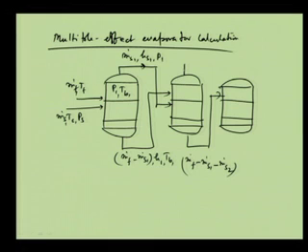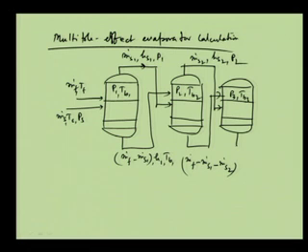And from here it is coming like this. So, this is the steam that is fed into the next effect. Here it is m dot S2, that is quite clear, and HS2 is the latent heat, P2 is the pressure here, and Tb2 is the temperature here, P3 is the pressure here, and Tb3 is the temperature over here. And here again the condensate, the product, is coming out, and this product would be m dot f minus m dot S1 minus m dot S2 minus m dot S3, okay, which has enthalpy H3 and Tb3 as the boiling point.